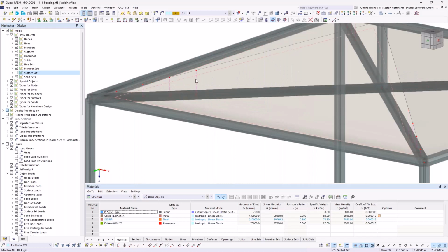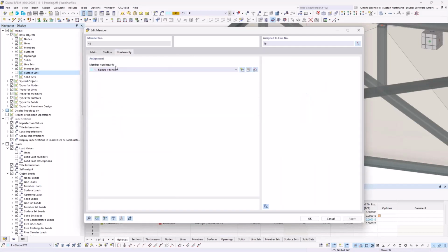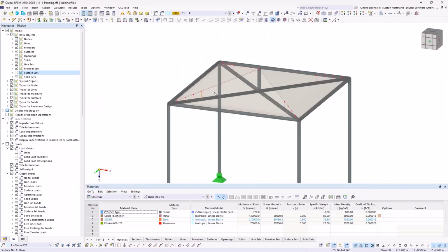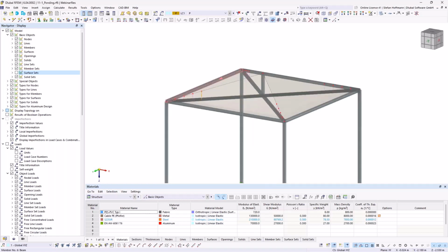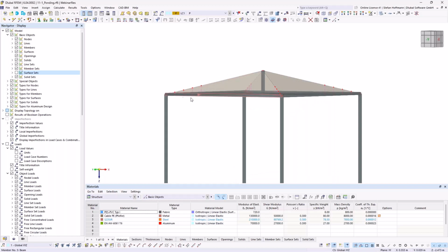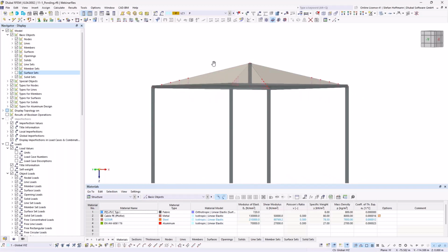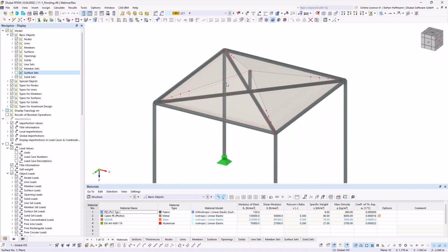And I tried to couple my membranes, as you can maybe see, with some rigid members, where I gave them some nonlinearity. Because if some elements are not connected with our FE mesh, there's no check if the membrane will deform quite a lot below the member, so that they will touch and distribute forces into each other. That's usually linked to hydrocords or independent meshes. So I will try to at least model it in a small part so that the membrane can lay down on the member, so that the behavior of the membrane is most likely like I would expect in reality. Line releases are not allowed for such a type, so you may use such couplings. They were also introduced in RFEM 5 already, and they may work.